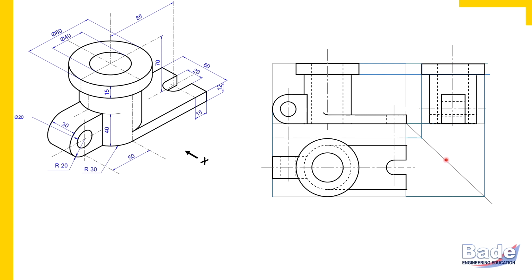And this is how here there is a dotted rectangle. Can you see that dotted rectangle? Remember, each and every part you must be able to identify. Each and every surface, each and every edge you must be able to identify in orthographic views. Now, this horizontal plate, its largest surface is in the top view. In the front view, it is a rectangular strip, and in the side view also it is a rectangular strip. Watch here. This horizontal dotted line, 60 millimeters from left to right. This is just the top surface of the plate.